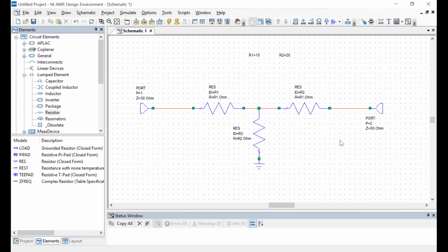So I can connect the ports, and this kind of network is made with resistors, so obviously this is not a lossless network. It's actually used to build attenuators. Now, if you look at the circuit, let's call port 1 the input and port 2 the output, though it should not matter. The situation is not only reciprocal, it's also perfectly symmetric now. You can't really distinguish which one is port 1 and which one is port 2.